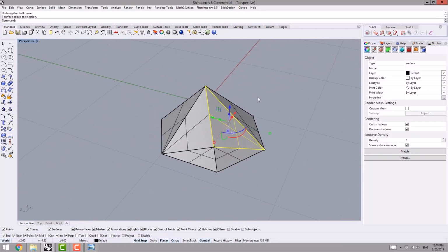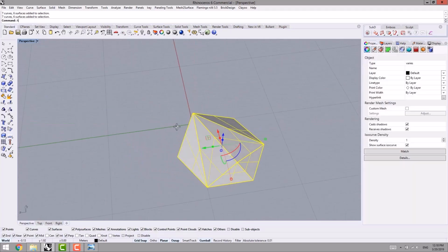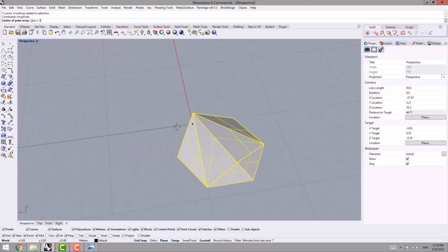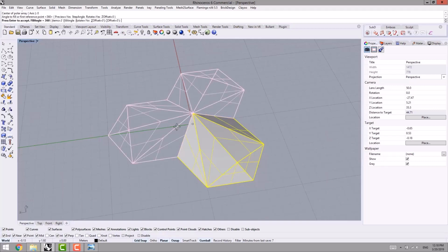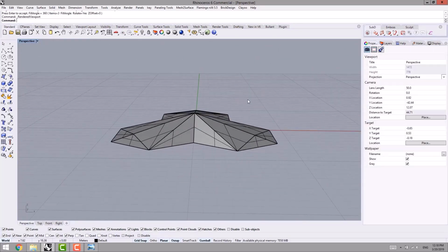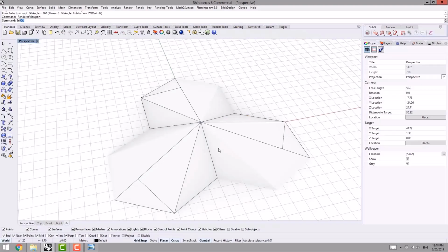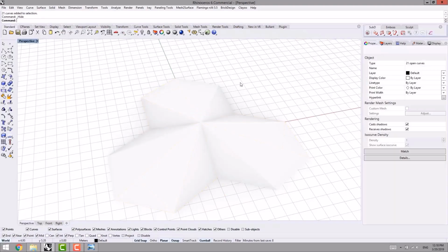As you can see. Very well, and then I select the created surfaces to array them. I start array polar. I specify the center, then the number this way. Well done. So in this order we can create one of the panels. I select the curves.